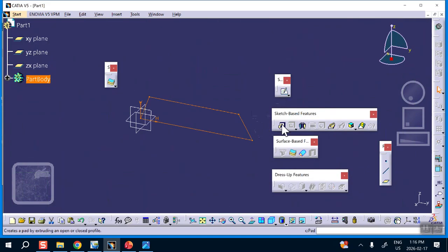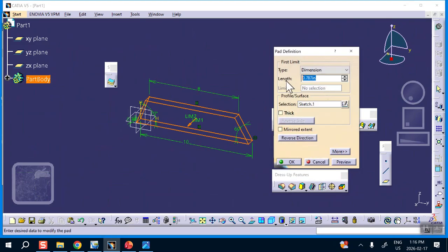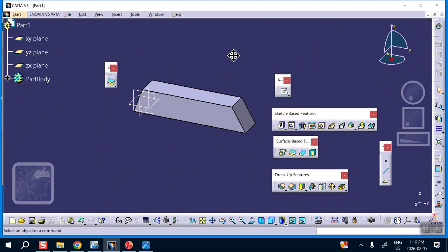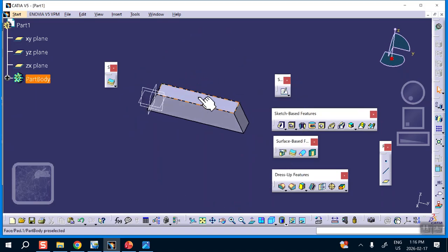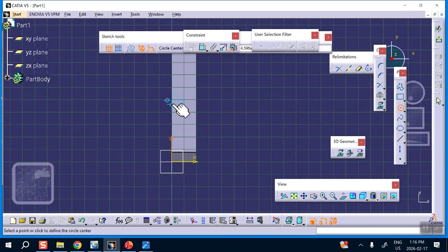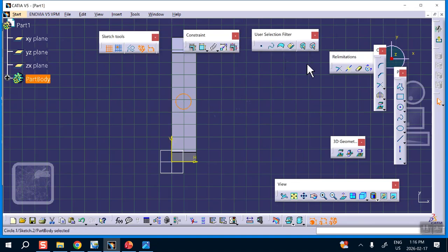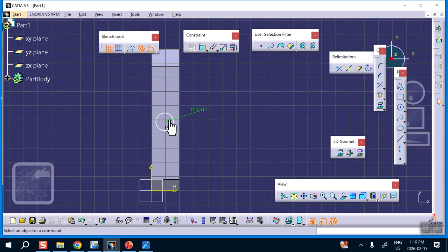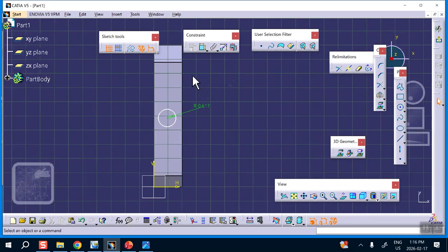Now notice that the thickness of this is given as a constant number, 2 inches. So it's not a parameter, I just make it 2 inches. And then we're going to create our circles. On the top, we will sketch a circle and dimension it, because later on that's going to be our top. I want to make sure that this is exactly halfway. So one way of doing that is, for example, let me try this. I select this point.